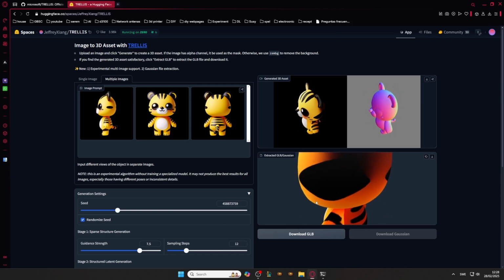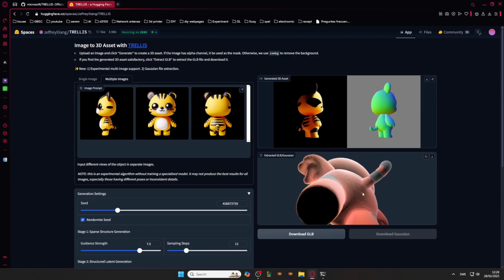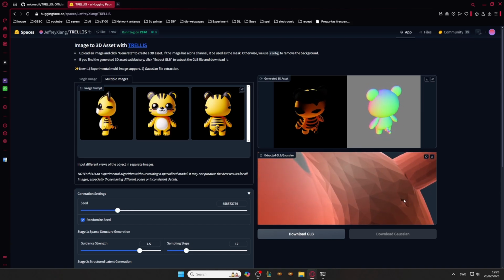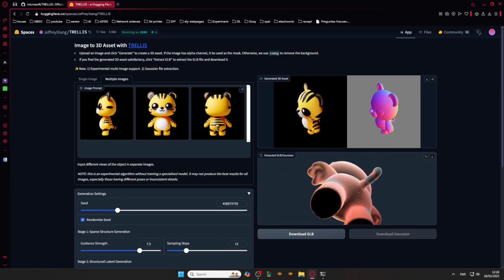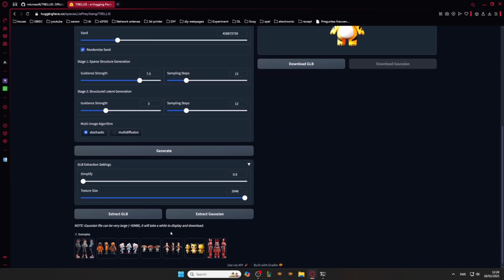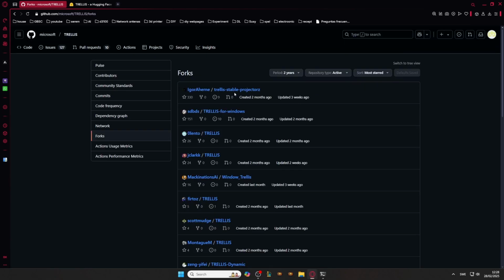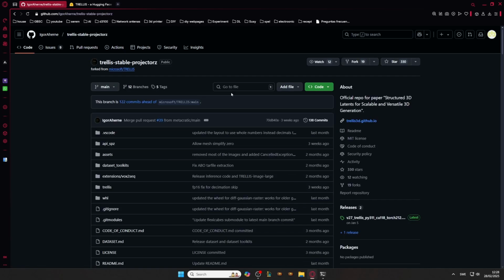I have imported these in Blender, and I'll show that later. The difference between the modded and the non-modded. And the lower you go, the more defects you have, like the small holes there. So the difference is in the mesh from the Hunyuan, that it has some small holes, and sometimes it has volumes inside the object. So it's empty space. And for 3D printing, that's really bad.